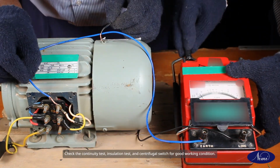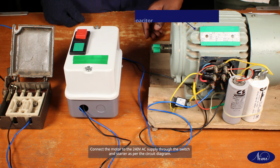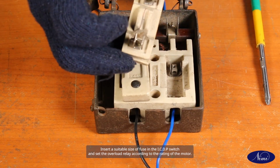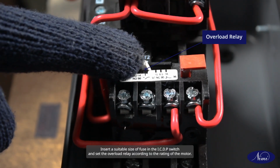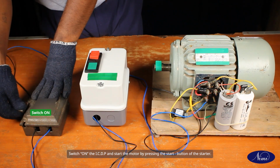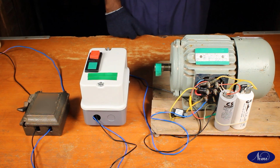Check the continuity test, insulation test and centrifugal switch for good working condition. Connect the motor to the 240 volt AC supply through the switch and starter as per the circuit diagram. Insert a suitable size of fuse in the ICDP switch and set the overload relay according to the rating of the motor. Switch on the ICDP and start the motor by pressing the start button of the starter.